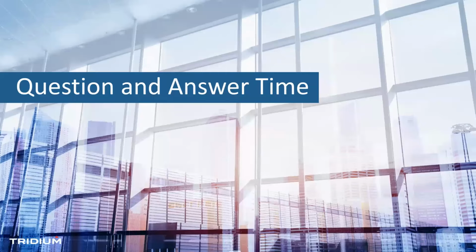I think 36 is good, but in many cases there are people that have gone beyond 36 and added some specialized ventilation requirements. I worked with a local university where they increased the ventilation and added ventilation sequences to pre-flush buildings early, before students get in the building. This was all as COVID hit, but they still use those today because they found it's a best practice. So I think the new ESG requirements, and again, we'll push that. But definitely within the guide spec, you can put your sequences.